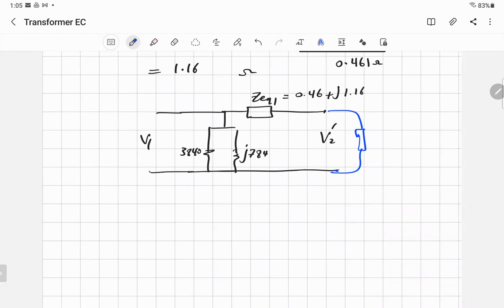We don't say that in engineering speak. When you have a transformer, you have a load. If you know the load, you give them the power and the power factor. So what's the load that you're using the transformer for? Well, 300 watts, 0.87 lagging power factor. That's the language you speak. All right, we translate maybe to ohms.